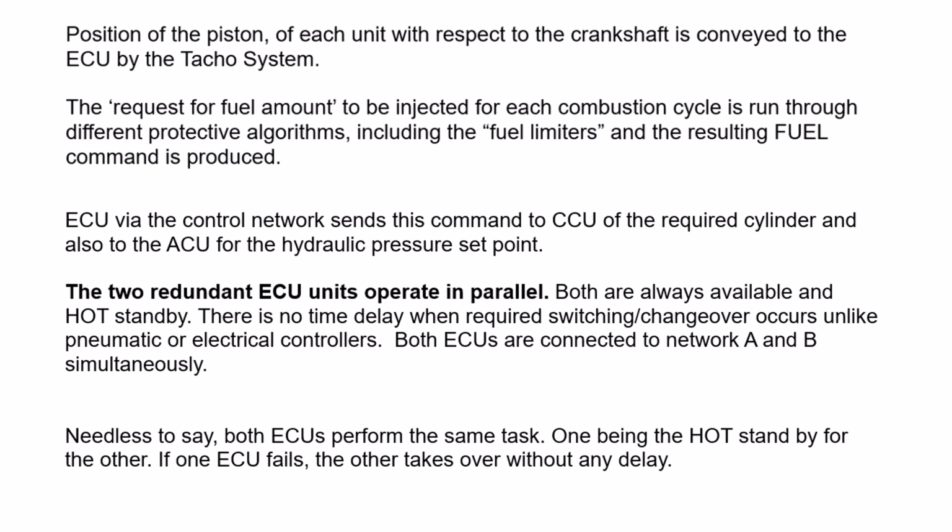Position of the piston of each unit with respect to the crankshaft is conveyed to the ECU by the tacho system. The tacho system has to know the position of the piston of the particular unit in question with respect to the crankshaft, so that the particular unit activity as required in the cycle can be carried out, with a fuel injection or exhaust valve opening or whatever.